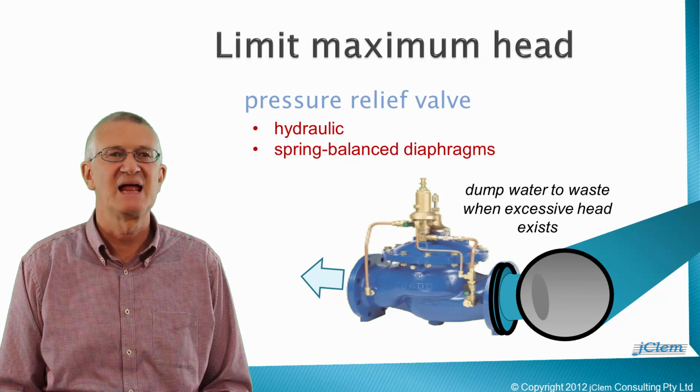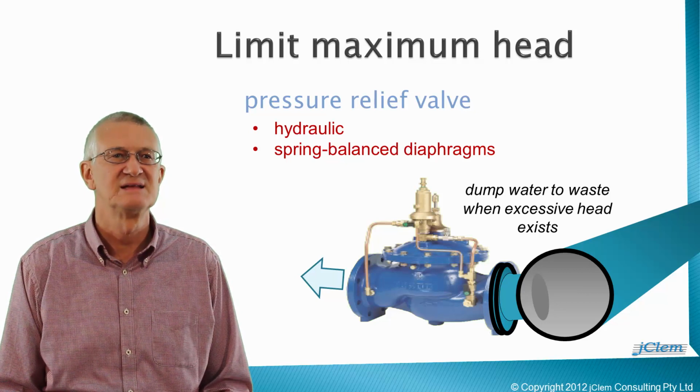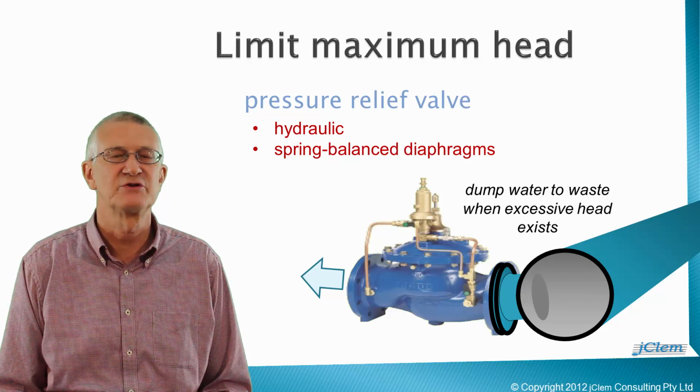They can be an inexpensive and effective solution in the right circumstances. However, transient analysis needs to include the effects of pressure relief valve closure in the context of the prevailing system fluid velocities. In some situations, pressure relief valve closure can introduce an additional unacceptable transient event.